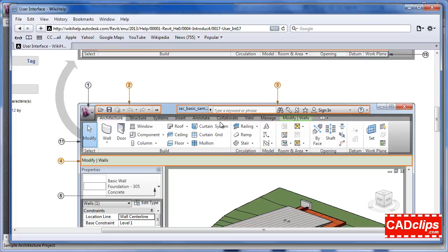You can go on to any tool inside of here and right click and say add to quick access toolbar, and it's like a little palette. And if you expand this and pick on the far right, you can move this quick access toolbar to be below the ribbon, which is this area inside of here. So this is handy for placing your own favorite tools on any tool.